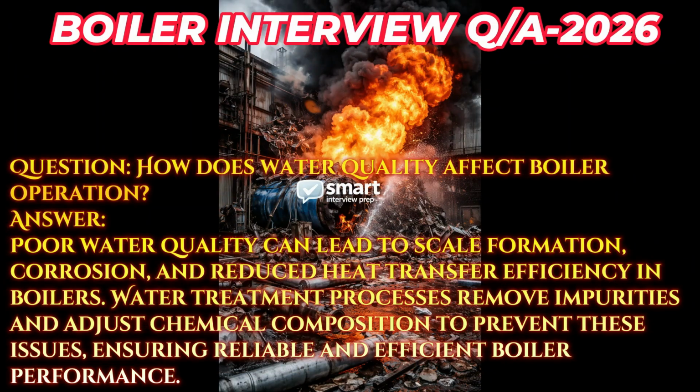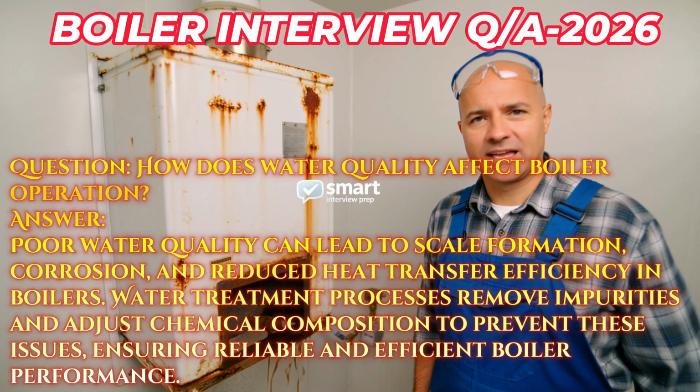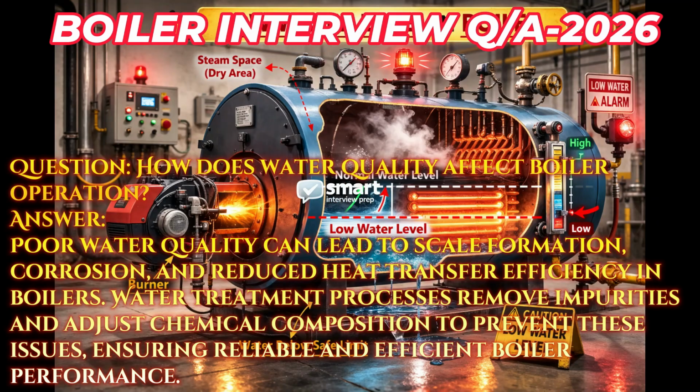Question: how does water quality affect boiler operation? Answer: poor water quality can lead to scale formation, corrosion, and reduced heat transfer efficiency in boilers. Water treatment processes remove impurities and adjust chemical composition to prevent these issues, ensuring reliable and efficient boiler performance.